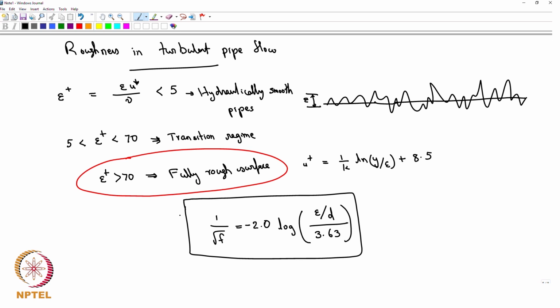Epsilon is for the pipe. So that's why it's independent of the fluid flow. Except, wait, delta P will still depend upon the fluid flow. F is a non-dimensional quantity, and therefore it's independent of fluid properties. You will get an F, and when you connect your F to, let's say, hf and then to your delta P, all the properties, density, viscosity, everything will come in. So that's another beauty of non-dimensional numbers, that you are getting everything independently.